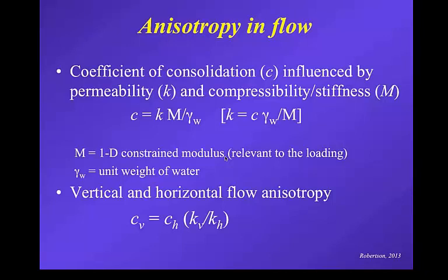It's not a perfect interpretation, but generally accurate to within about an order of magnitude, unless the soils are very soft and homogeneous, where it's a lot more accurate. If you've got soft, normally consolidated clays, then you can get quite good interpretation. But anything outside of that, the stiffer clays, the silty clays, the clayey silts, and the silty sands that tend to be a lot stiffer, the dissipation curves are more complex and the accuracy less good, and hence that's why I say within an order of magnitude.